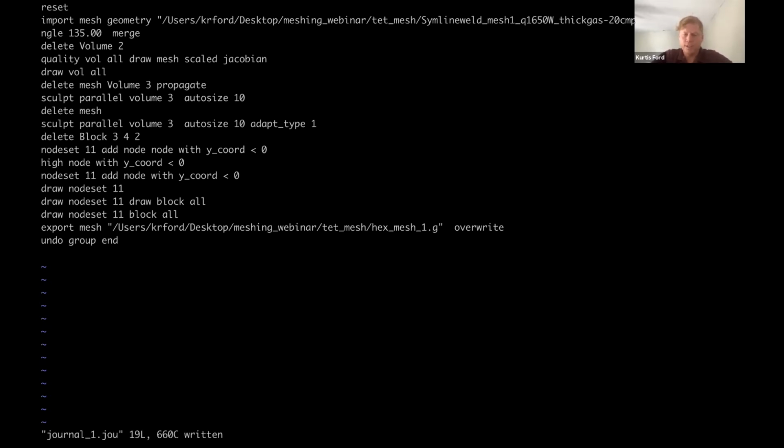Another thing you can do is templating tools. I use Jinja, which is a Python library, and that's very powerful. And that's handy if you're doing other things like I was in this model, where Cubit isn't the only thing that you're dealing with. Jinja is really nice because you can template everything you're doing. But you can also just do it inside of Cubit, and that's what I'll show you how to do.